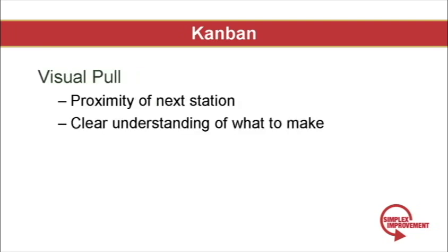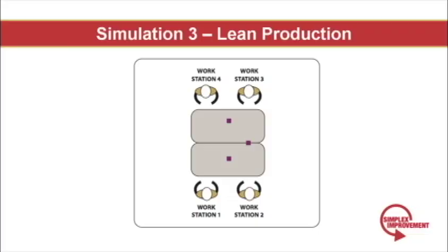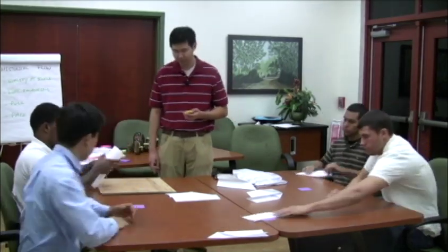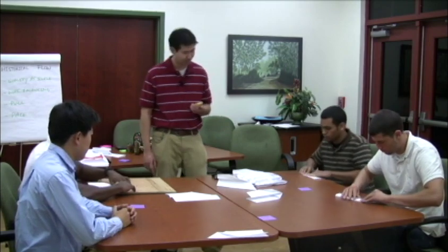The first type of Kanban is a simple visual control that tells the worker when to produce and, more importantly, when not to produce. Notice that the simple use of a post-it note that serves as a Kanban is a simple way for workers to communicate non-verbally. In a case where work flows one piece at a time through the cell, a visual pull may simply be an extended hand from the next worker. Remember, proximity and simplicity are the keys for the system to work.